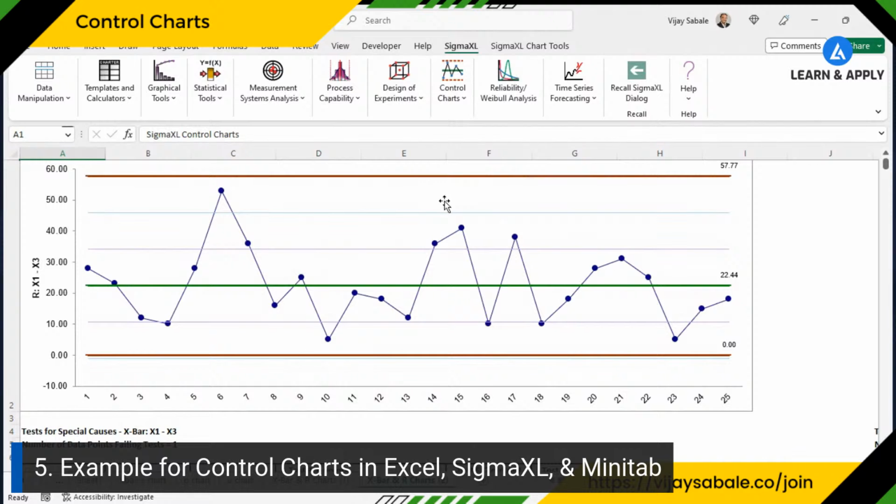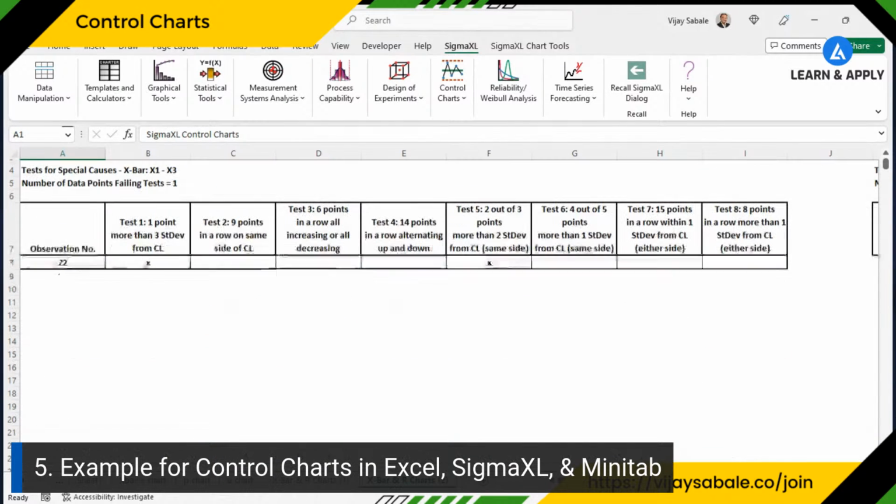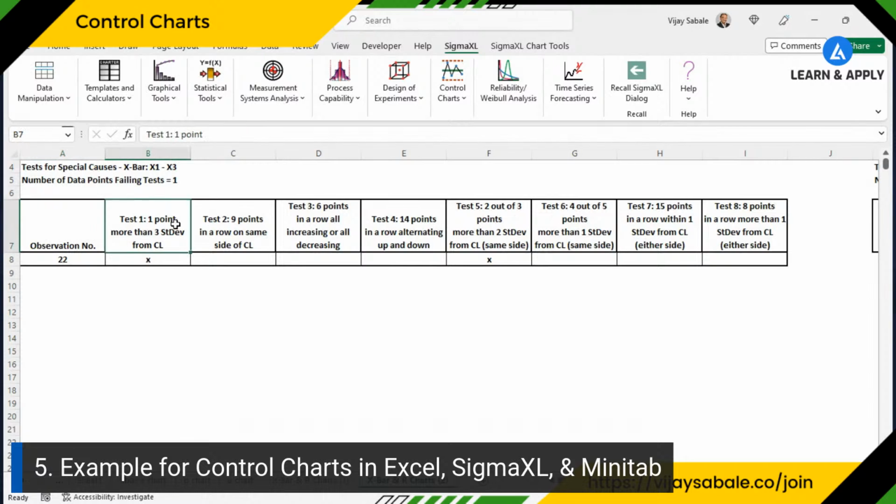Yes, we can see everything is in control. So we can go for the X bar chart. And again, it is indicating the point number 22, which is failing test number 1. If you go to the detail, we can also get the 8 Nelson rules. What are these 8 Nelson rules? And out of these 8, for which data point, what are the tests for which we are failing? Like observation number 22, that is failing test number 1 and test number 5.